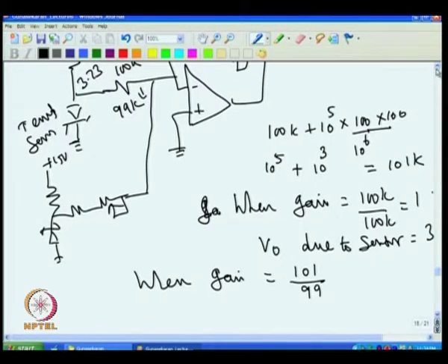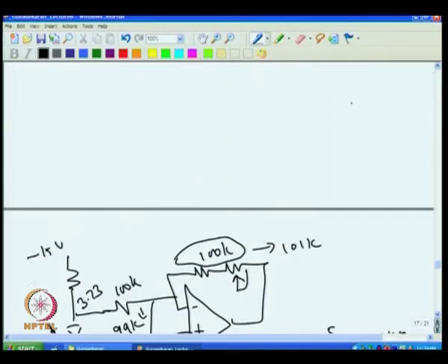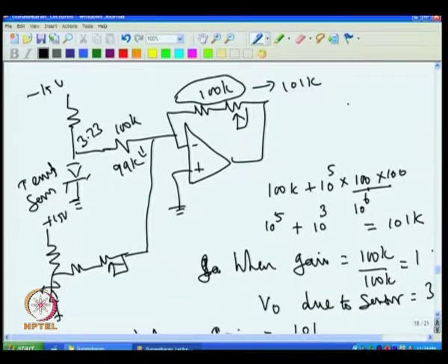The old circuit that we discussed in the previous class is this. Here we used the LM335 as a temperature sensor, and this gives you 2.73 volt at 0 degree C. To subtract that, we used the LM336 as a 2.5 volt Zener, and then we selected this resistance and designed the temperature indicator. And then we also discussed the errors involved in this.